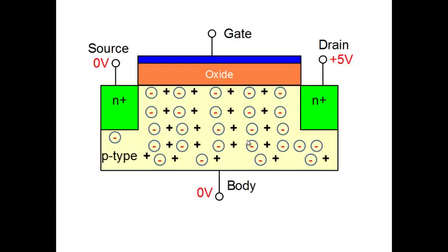All right. So again, what we are doing in this particular case, note that this is the picture. Let's say when you apply 0 volt, the region is full of holes and you have ionized acceptor atoms, and there's no channel between the source and the drain. You apply increasingly positive voltage. Now, when you apply positive voltage, what you're going to do is push away the holes from here. The holes are going to go here, come out of the body, and eventually that positive charge is going to travel and come over to the gate here, right? So positive charge will be at the gate, leaving behind the ionized acceptor atoms here.